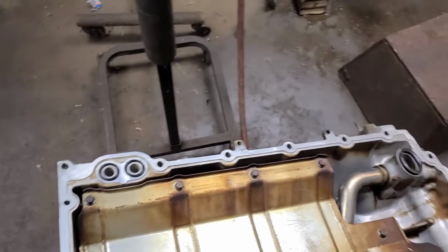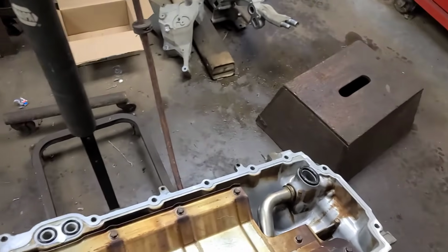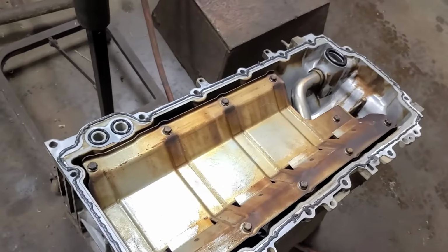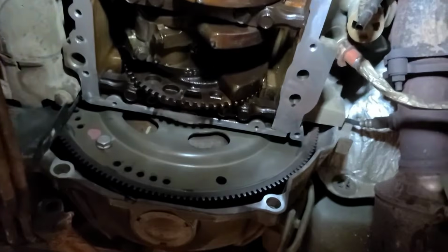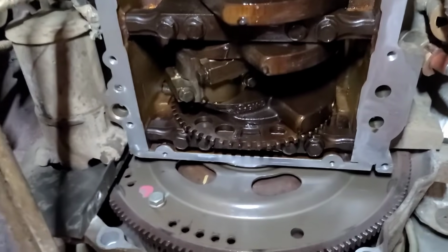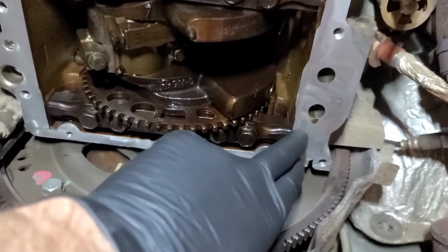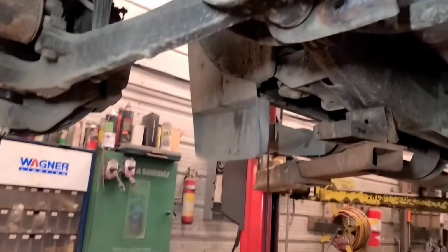Now we're going to clean up the block and get ready to install the oil pan. So there's a bead of sealant, about 1/8 of an inch bead all the way around the outside perimeter, staying inside the bolts. Like I said, if you leave this sitting overnight, it'll drip less. I got to wipe this surface off here because there's a drop of oil here. Mind you, the O-ring is there, so it's not so bad. So we're ready to put the pan on.